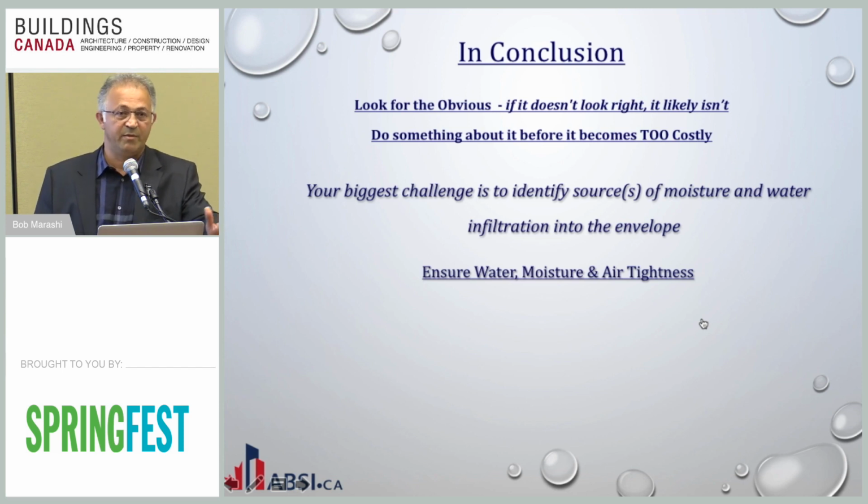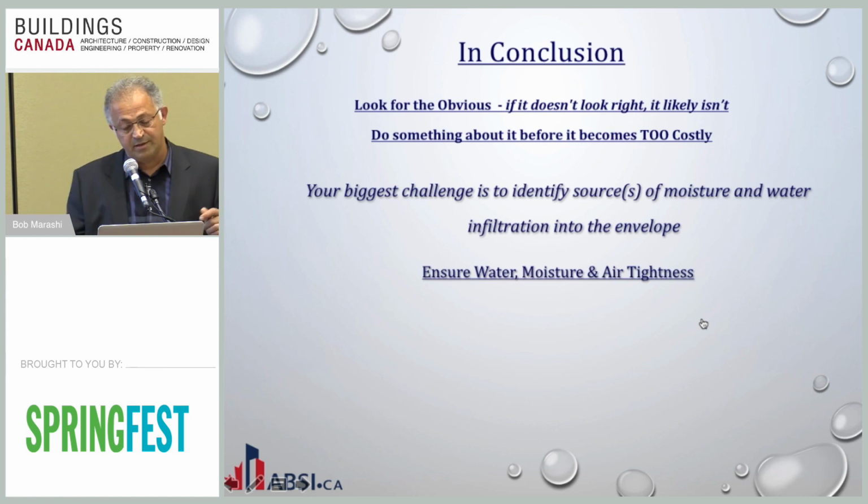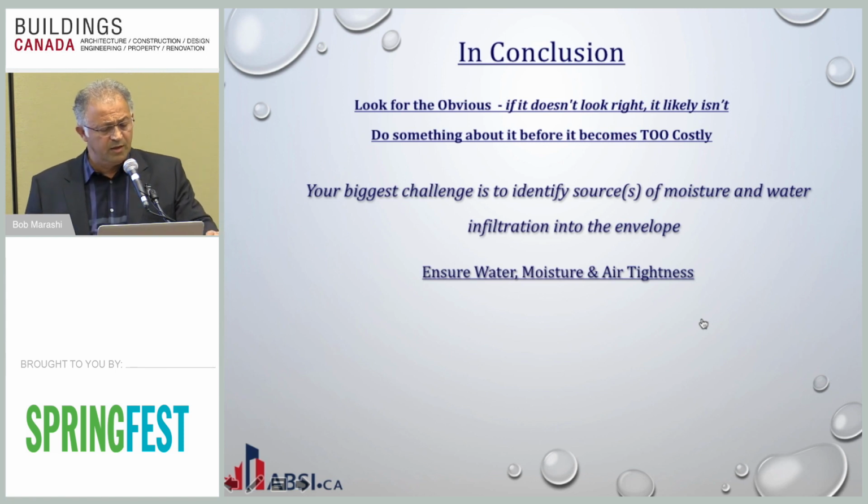Sometimes they're simple, everybody sees it. Sometimes they are not. You actually have to get on your knees, open the wall, do a little cut test, throw some water at it, wait for a little bit until you find the problem. But you can find the problem. Once you find the problem, fix it. Otherwise, it's going to damage other things. It's very important to ensure your building is water and moisture and airtight.